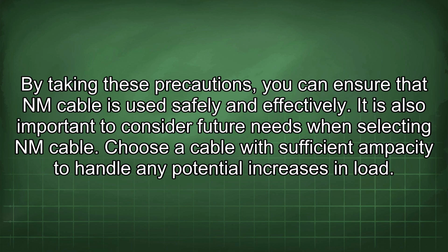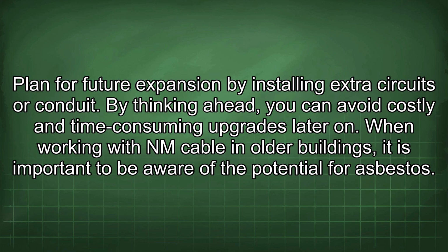It is also important to consider future needs when selecting NM cable. Choose a cable with sufficient ampacity to handle any potential increases in load. Plan for future expansion by installing extra circuits or conduit. By thinking ahead, you can avoid costly and time-consuming upgrades later on.